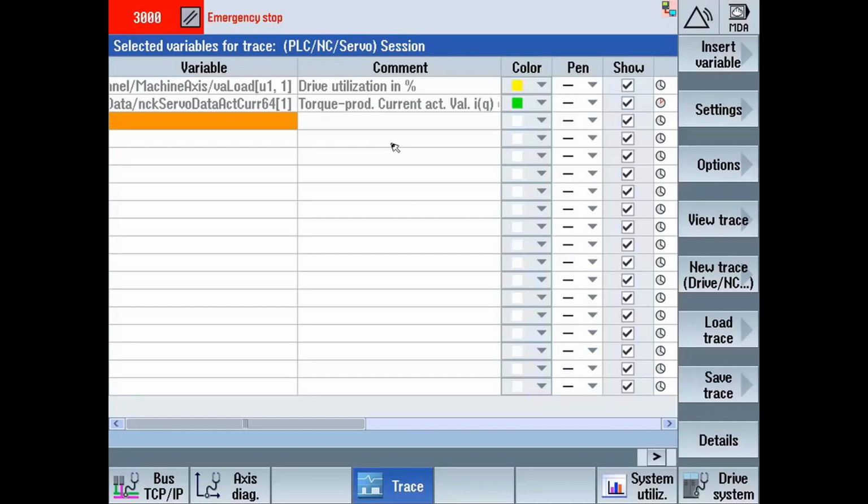If you're on a linear motor, all the words change to force instead of torque because straight versus round. But the point being, with the torque producing current, this is a good thing to use to see, let's say you have some kind of obstacle that you're running into, and you want to look and see how the machine behaves over the length of an axis travel. You would look at the torque producing current, and you could see that, oh, in such and such area or at such and such distance, I'm building up and I need more torque.